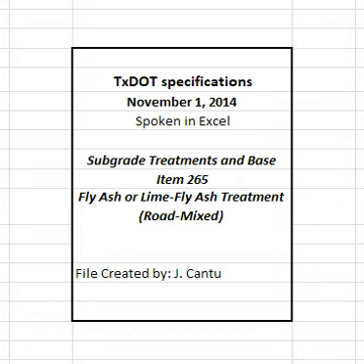2.4 Flexible base. Unless otherwise shown on the plans, furnish base material that meets the requirements of Item 247, flexible base, for the type and grade shown on the plans, before the addition of lime or FA. 2.5 Water. Furnish water free of industrial wastes and other objectionable matter. 2.6 Asphalt. When permitted for curing purposes, furnish asphalt or emulsion in accordance with Item 300, asphalts, oils, and emulsions, as shown on the plans or as directed.